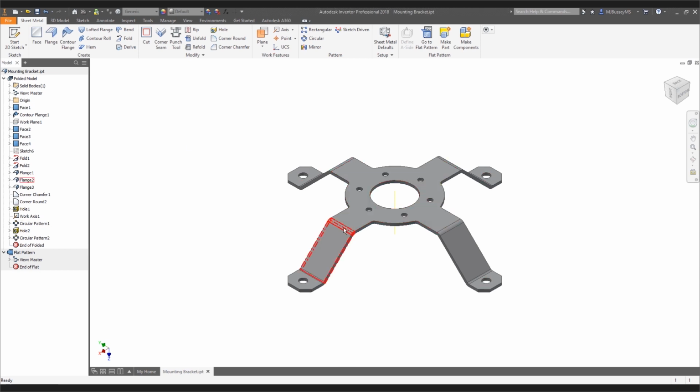I would love to see something like this on Idea Station, because what we'd wanted to see at some point is, hey, select the actual bend on the part or in the feature tree, and basically right-click on it and say, set unfold rule. So you can kind of multi-select things. It didn't happen. I would love to see it, but that's basically what you have to do.